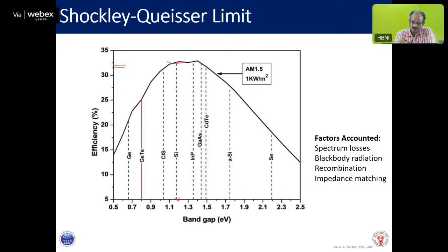These are for different solar cells. For an indium phosphide solar cell, we can have nearly the same. But suppose we have a solar cell made of germanium. Using germanium also we can make a solar cell in the same way: p-type germanium and n-type germanium, join them together, make a PN junction. But that will give a maximum possible efficiency of 21%.